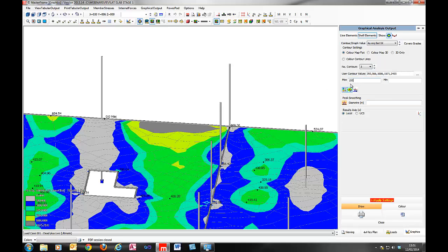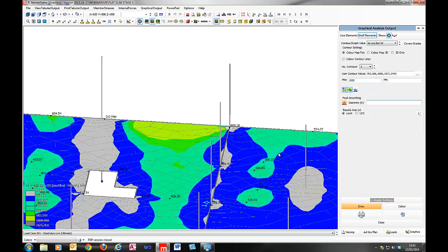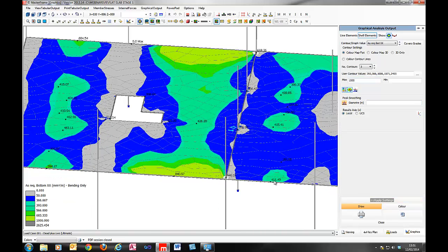And these max and min values help you to utilize your color a little better, so that points of singularity with erroneous peak high values that aren't smoothed out by the peak smoothing, you can filter those out as well using max and min values in these locations.